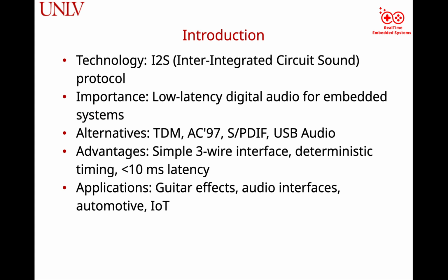I2S is simple, has deterministic timing, and supports very low latency, which is important for real-time audio quality in the digital world. It is typically under 10 milliseconds. That is perfect for applications that demand real-time response, such as guitar effects or audio interfaces, like I said.